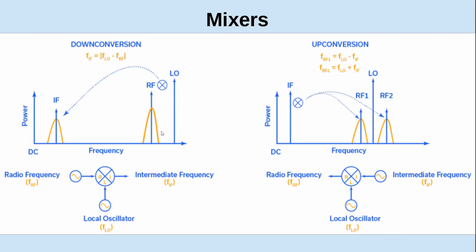So even though the RF signal is going to be somewhere between 550 and 1700 kilohertz, I think it's the AM band, the local oscillator is going to tune to 455 kilohertz one side or the other of your input frequency, depending on whether you want to get it up or low.